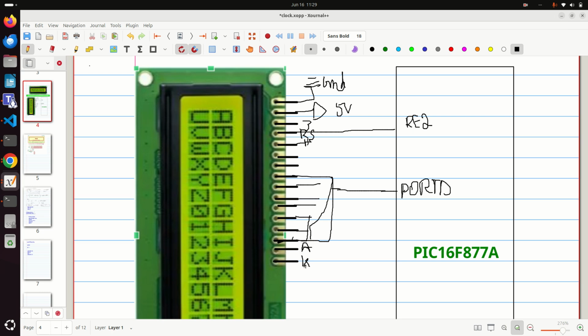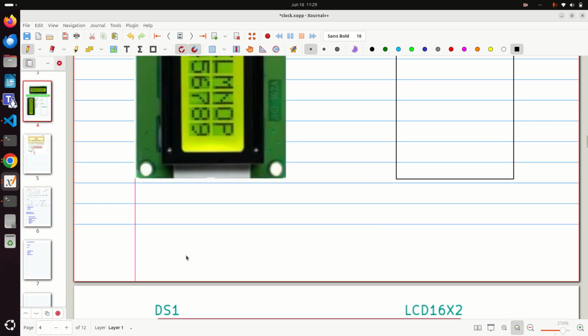So you can directly give the ASCII value to the data, to port D. How can you give it? Port D equals A. You can write like this: PORTD = 0x41.